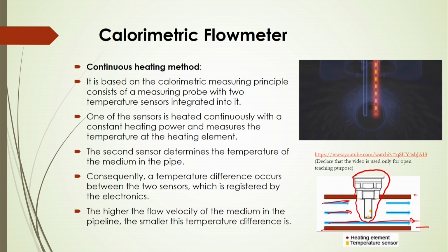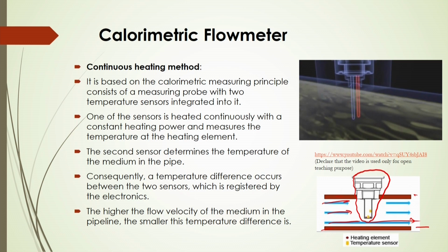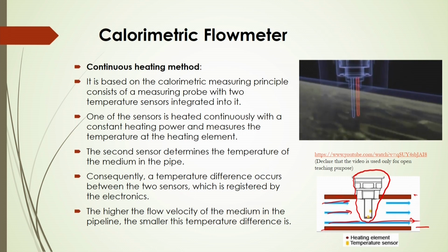From one sensor heat is supplied, and the other sensor measures the atmospheric temperature. When there is no fluid, no flow, these sensors will have the same temperature.